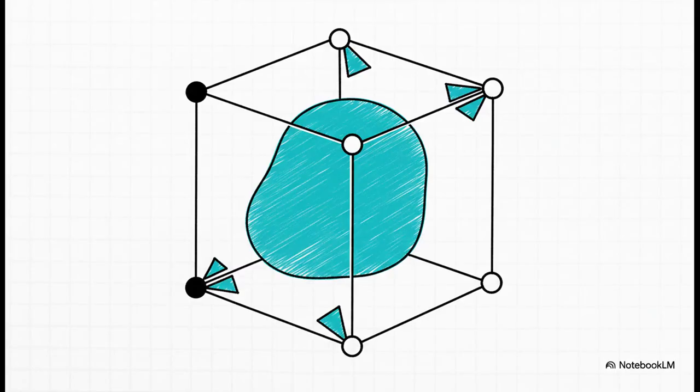And it does this by asking a really simple question. Based on a density value, like the known density of bone, is each of the cube's 8 corners inside the bone or outside the bone? It's just a simple yes or no for each corner. The surface that we want to draw has to pass through any edge that connects an in corner to an out corner. Simple as that.